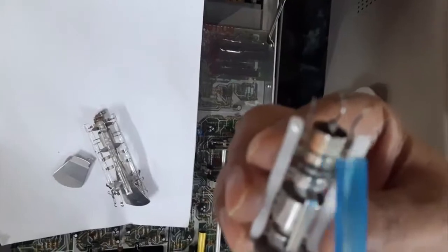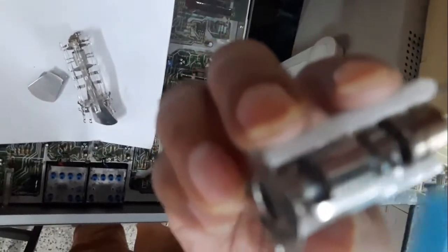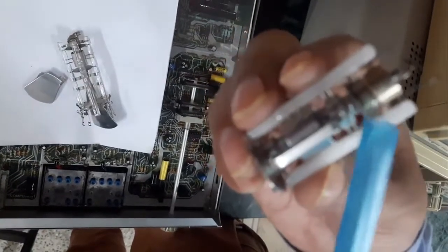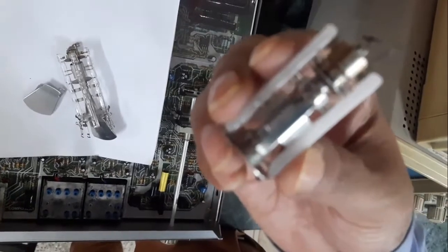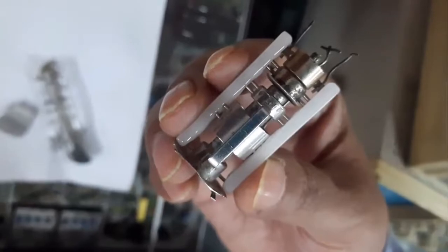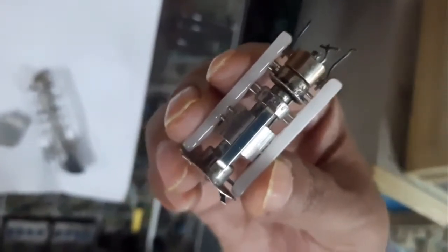We can find here that yes, this is a cathode. The cathode has strontium and barium oxide for production of the electrons. Along with this cathode, we have a nickel cylinder, which has a 0.25 mm drill at the center, so that a narrow beam of electrons can be created. The question is that if the electron passes through the nickel cylinder, it must have a small velocity. So to provide a high acceleration, to provide sufficient velocity, so that the CRT screen can be covered both in vertical direction as well as in horizontal direction.